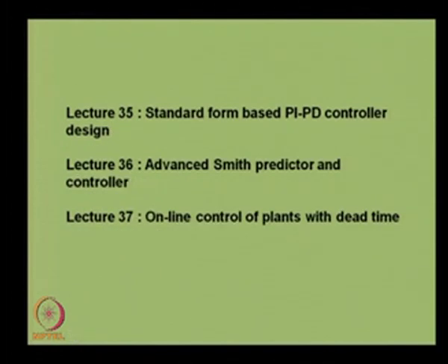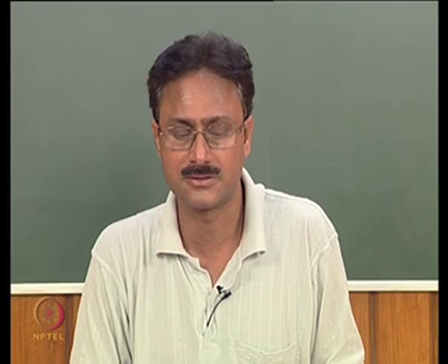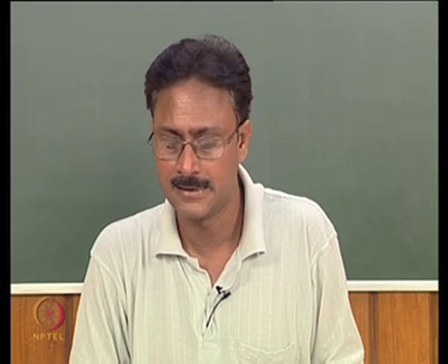Now, some advanced level of controllers to handle plants with long dead time, known as Smith predictor controllers, will be discussed in the 3 lectures, lecture 35, 36 and 37. Here we shall present one advanced Smith predictor controller which can be used for controlling stable, unstable and integrating plants.